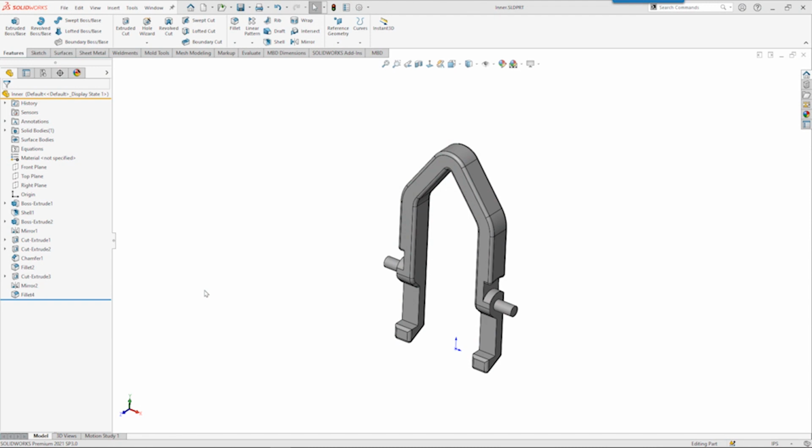This technique to investigate a part is pretty good if someone gives you a file or if you download a SOLIDWORKS model from the internet and want to see how it was modeled. If you look at the very bottom of the feature manager tree, there is a blue bar. This is the rollback bar. If you hover over that bar, you'll get the little hand symbol. You can grab that bar and drag it back in time to see how the part was modeled a feature